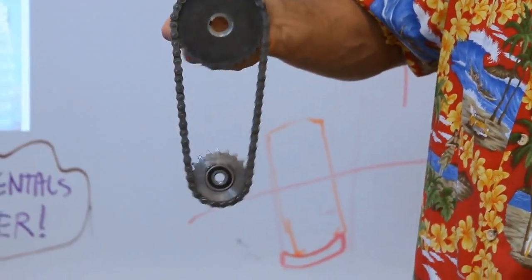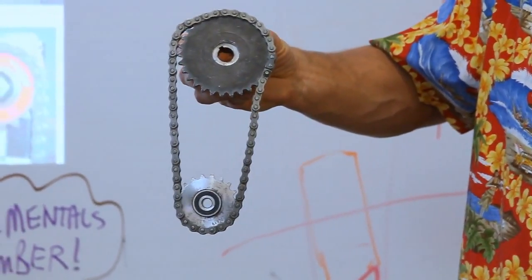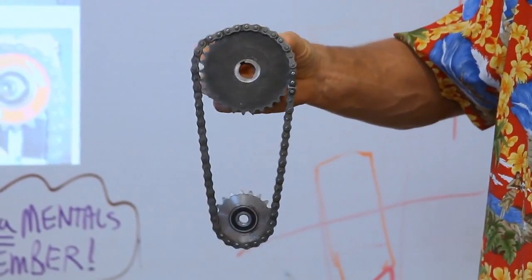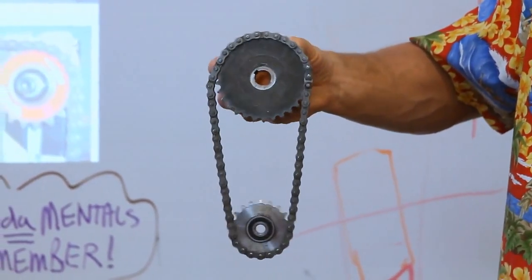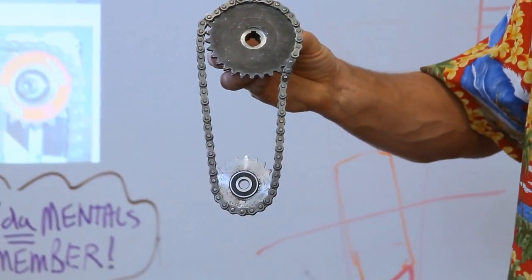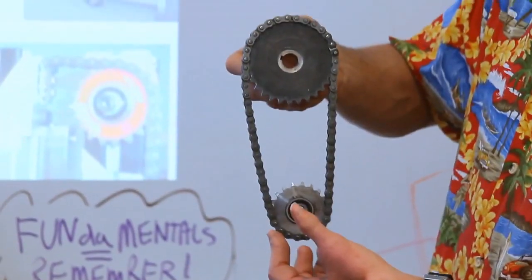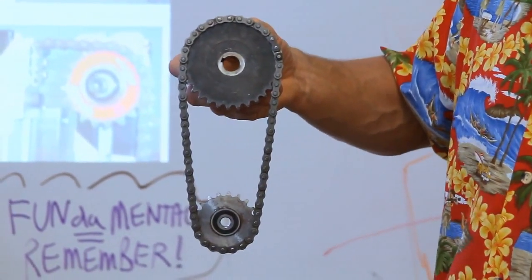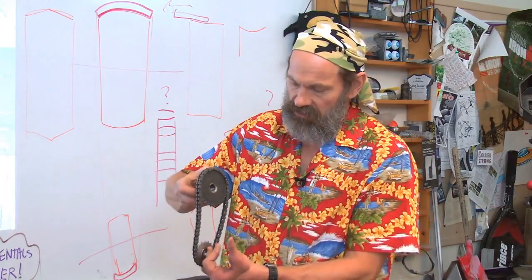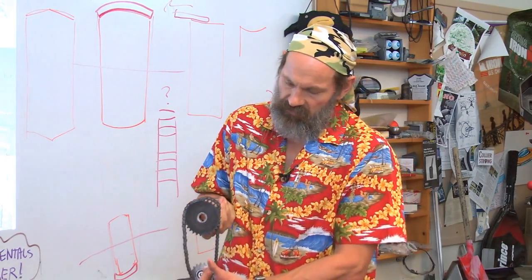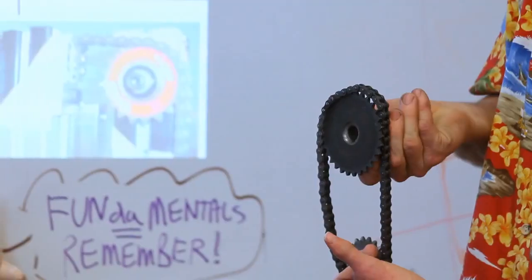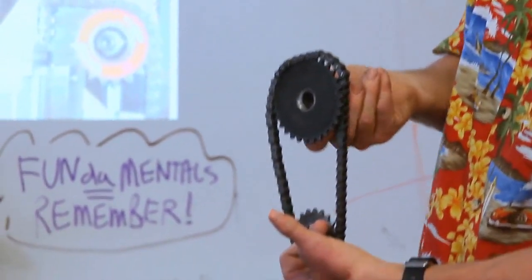See this motion here? And watch what happens if it's too misaligned. See the way the chain comes off? So chains are fairly tolerant of misalignment, but they're not infinitely tolerant. Anybody who's ridden a bicycle before and you're pedaling and you have an improper combination between the front sprocket and the rear sprocket, so the chain's at too much of an angle, you can derail the chain, which is a bummer. Which is actually how you shift gears, using the derailleur. It causes a sideways load that then will make it come off one sprocket and then ride onto the next sprocket.